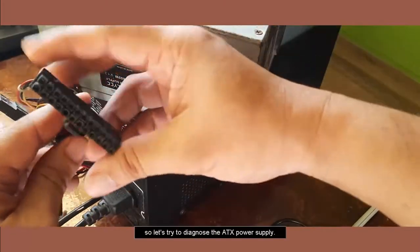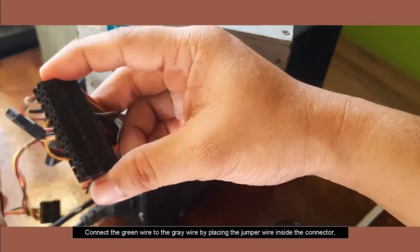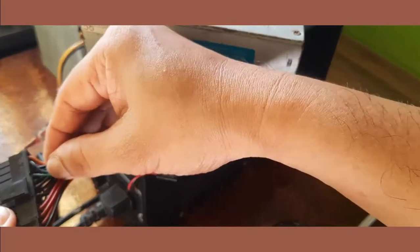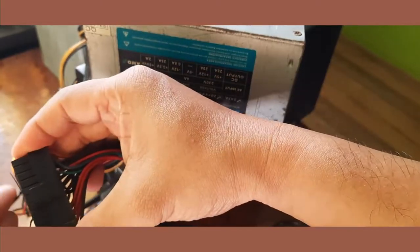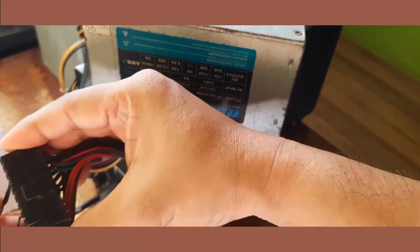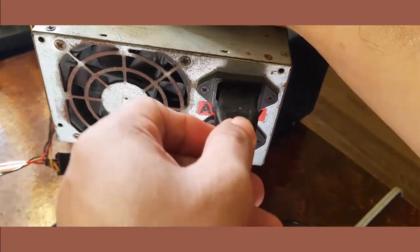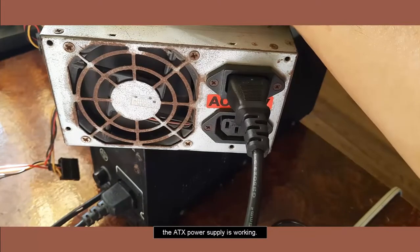Okay, so let's try to diagnose the ATX power supply. Connect the green wire to the gray wire by placing the jumper wire inside the connector and then plug in the power cord. As you can see, the ATX power supply is working.